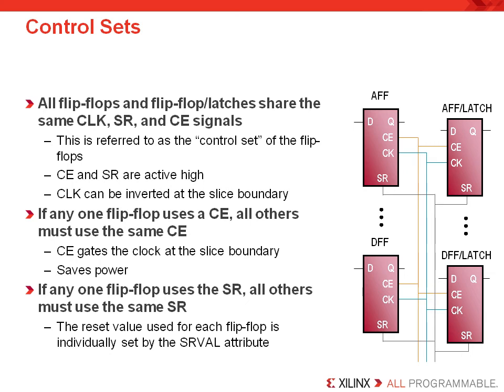But we would always tell our customers it's important to evaluate and reduce the number of control signals you have in your design, and try to eliminate all your low fan-out control signals that maybe only go to teens or 20s or even low hundreds of flip-flops. In that case, it might be a really good idea to try and share as many control signals with other logic if at all possible. So always evaluate your control signal usage and try to manage their fan-out.